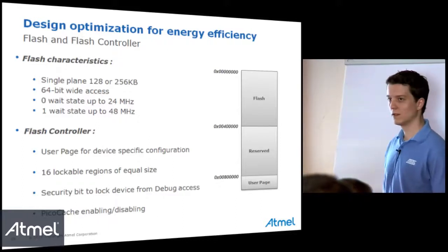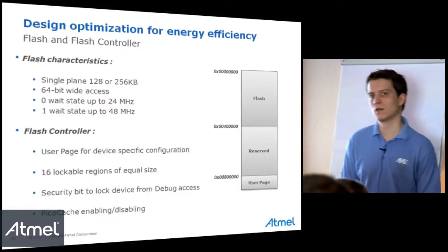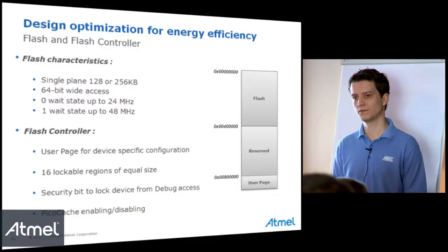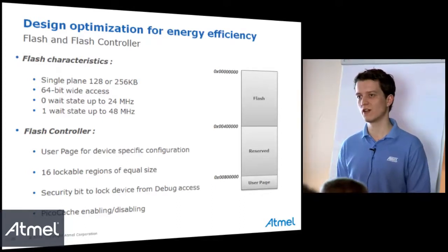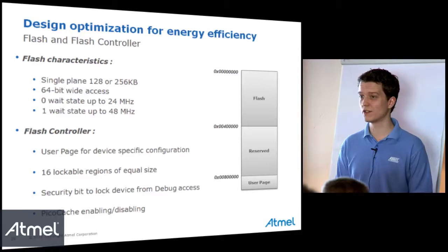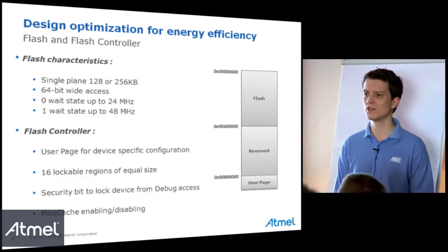Is it a fuse bit or a flash bit? I mean, if I do a full erase. No, it will not be erased. If you make a full erase, it's a fuse bit. Yeah, it's a fuse bit. As soon as it's set, you cannot reset it. Even with a full erase, I think there is no erase pin on this device.